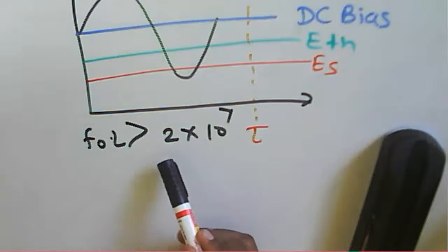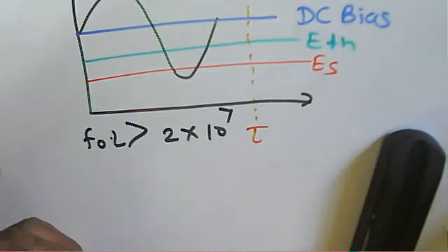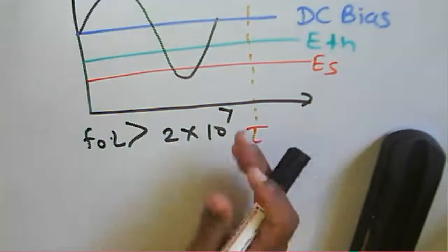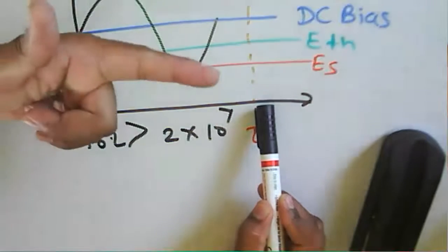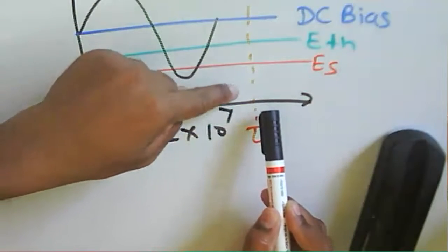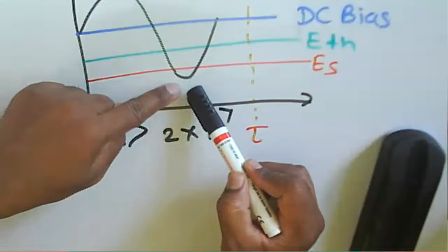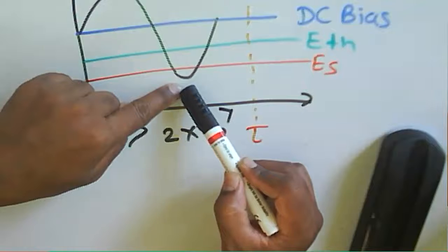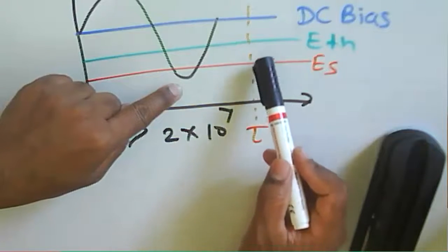In the quench domain mode, the oscillation frequency is determined by whatever resonance circuit we are using, instead of the transit time. This one is about the transit time. A new domain starts. Here below this it drops. Drops means what? Then it will be collected at the anode, and then a new domain starts at that point at this particular transit time.